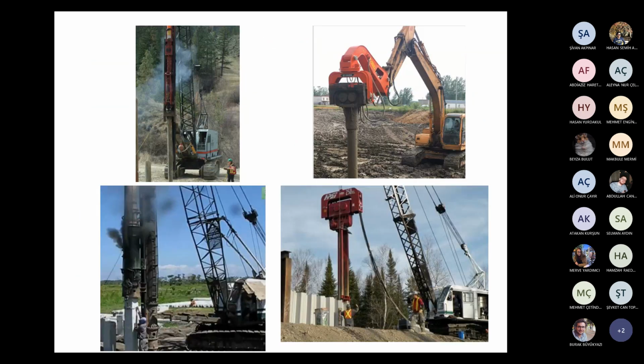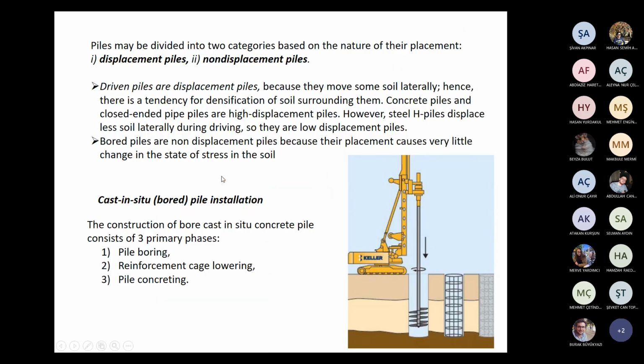Let me show, yes, here. When we drive this pile, whether by using vibratory driver or by hammering, this pile volume inside the soil results in a lateral force along the sides and finally results in densification of surrounding soil, resulting in displacement of soil.